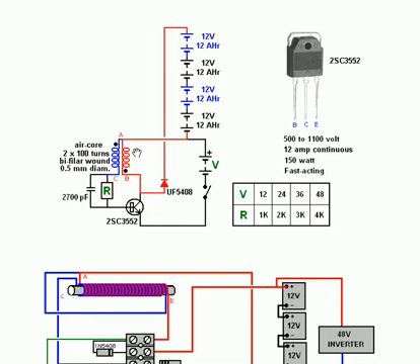There are 100 turns of each of those wires, and they're wound side by side throughout. The two wires are first a red wire, then a blue wire, then a red wire, then a blue wire. And while that sounds complicated, it isn't really. You just wind the coil from two separate strands of wire, and the wire itself is about 0.5 millimeters in diameter.